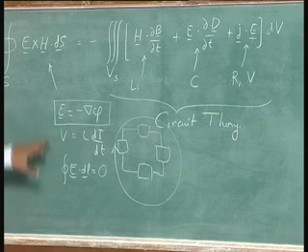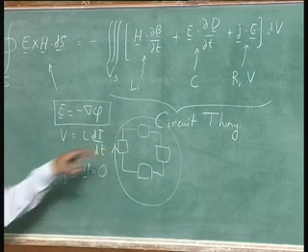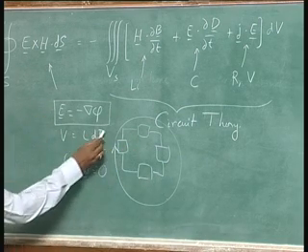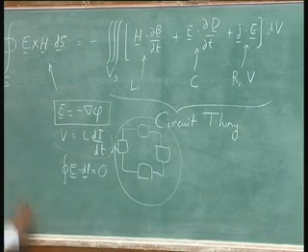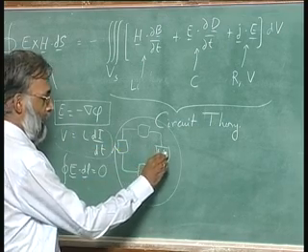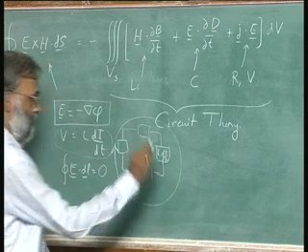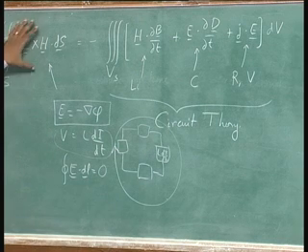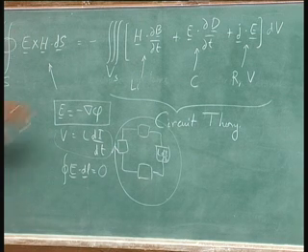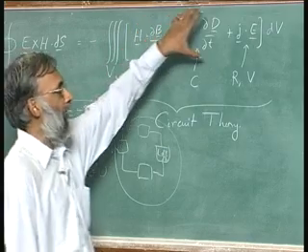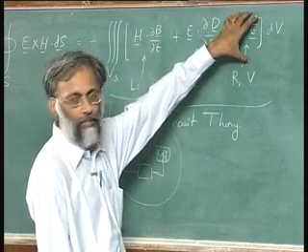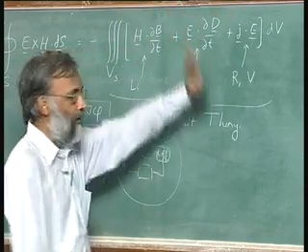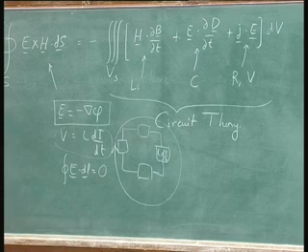That is what this is saying, and that is what this is saying as well. The place where this fails is inside an inductor, but we explicitly take inductors into account. We do that because inductors are really low frequency elements, so we can take care of them without invoking waves. So, magnetic stored energy, electric stored energy and dissipation and batteries is already part of our theory of circuits.